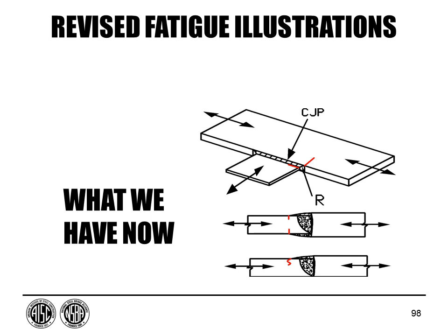One of the things that they show are these arrows. A double-headed arrow in these sketches represents stress range, cyclic, back and forth if you think of it that way. The welds that we're talking about, and very importantly, these red arrows, or red lines, show where the cracking is expected. So notice for this connection, the stress range is running longitudinal. This is a flange maybe with some attachment on it. Where's the crack shown? Well, growing into the base metal at the termination. Why? Because remember we had the high stress concentrations at the terminations.